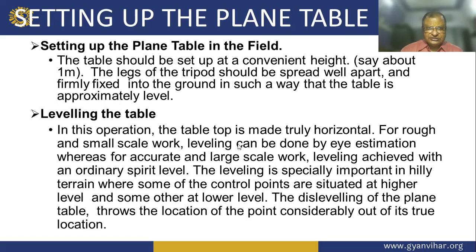Now, setting up the plane table in the field. The table should be set up at a convenient height, and the legs of the tripod should be spread well apart and firmly fixed into the ground in such a way that the table is approximately level.